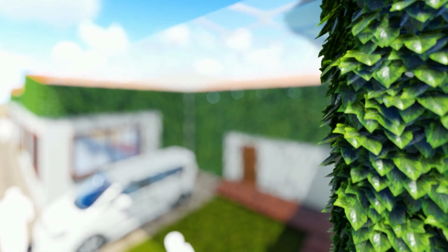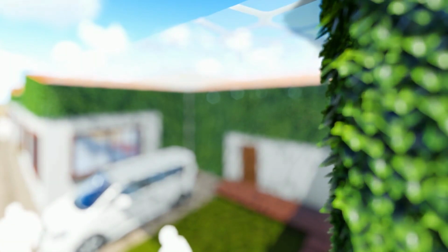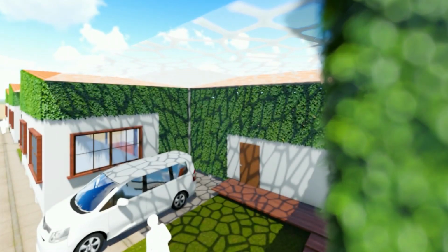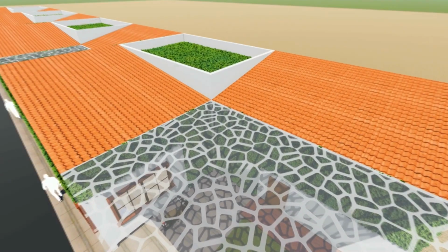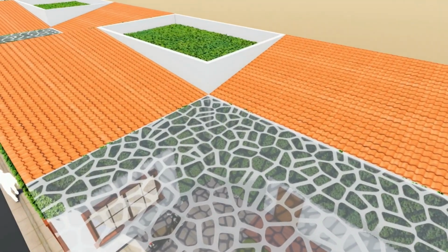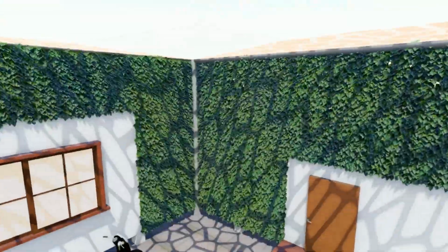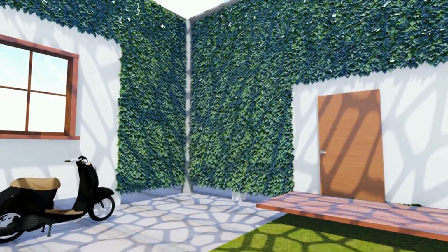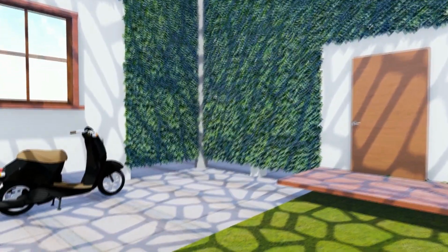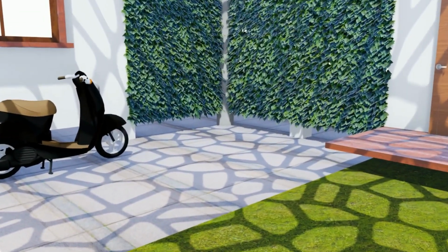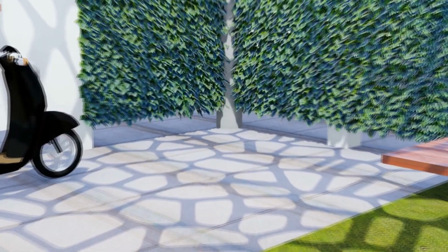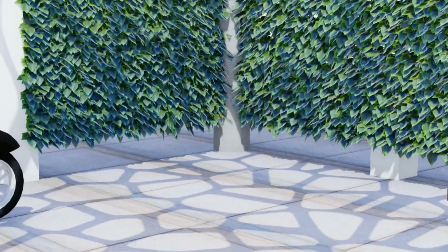Some of the methods which I will be implementing for the particular site are adding green walls, which help in maintaining the thermal comfort of the building and purify the air of the surroundings, and rainwater harvesting for collection of excess water and reusing it. Looking at the weather conditions of Naga City, the row houses have been given a higher plinth level so that the building is less affected during floods, and it also helps in collecting the runoff waters.